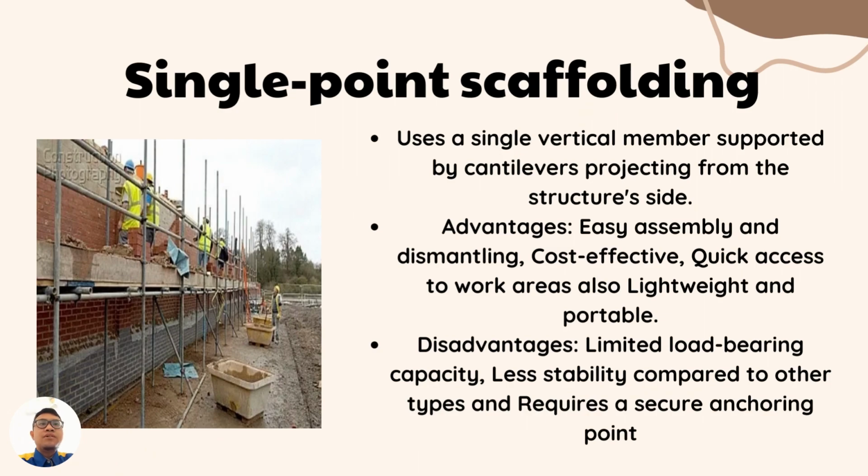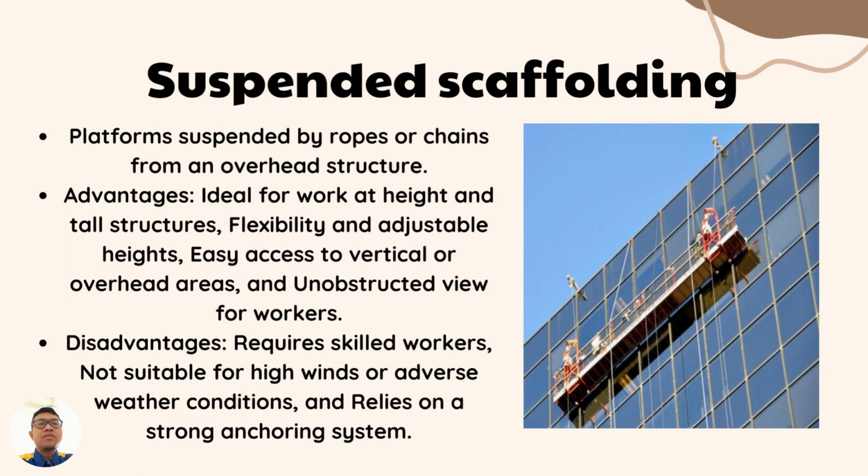The advantages are easy assembly and dismantling, cost effective, quick access to work areas, also lightweight and portable. The disadvantages are limited load bearing capacity, less stability compared to other types, and it requires a secure anchoring point. Next is suspended scaffolding.